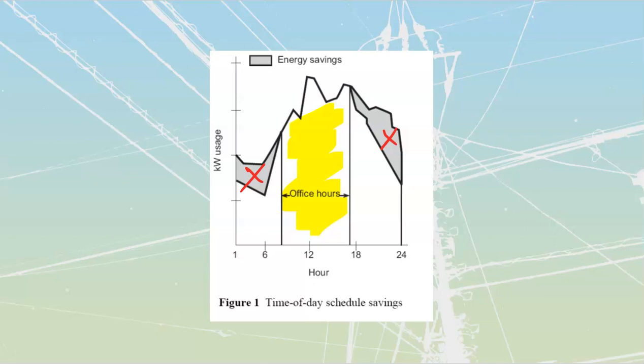You can't just shut off all of your public lights. Washrooms usually don't have windows, so you don't want to be shutting those off as part of it, or there should be night lighting inside of them, things like that. So it needs to be done intelligently, but there are ways that you can use your HVAC systems or your building control systems to cut down on the amount of usage, because ultimately